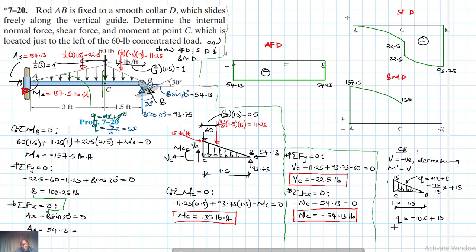Okay, so therefore our shear in the region CB, our shear from C to B, is going to be equal to, the initial value at C is what? So you always focus on your shear force diagram, is 82. I know they are all negative this time around. Now I'm going to subtract them later on when I've calculated the moment is negative. I don't want to include the negative. Okay, but I'll subtract everything else after I've converted this to moment. Our initial value is 82.5.